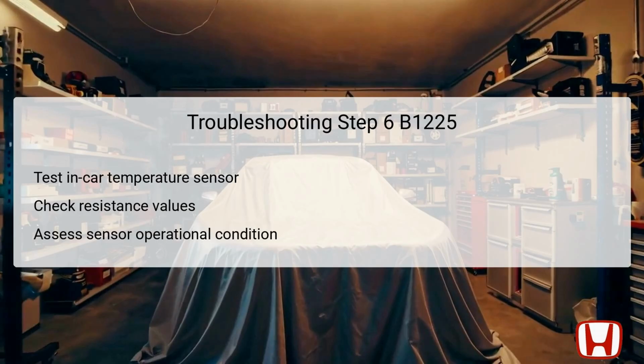If you confirm that the temperature sensor is working properly, it will lead you to the next step in the troubleshooting process. However, if the sensor fails the test, it is essential to replace it to restore proper function to the climate control system. The in-car temperature sensor is critical for regulating interior temperatures and ensuring passenger comfort, making it essential for the vehicular climate control system to operate effectively.